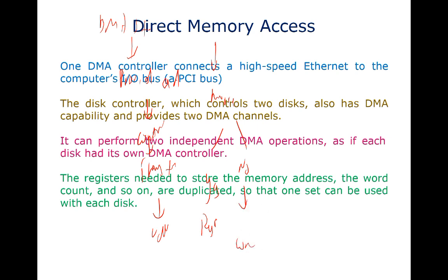Now we also need to know what happens when the DMA transfer completes. The processor is freed from continuous involvement in the actual block transfer, and it is notified after the operation is complete. A simple technical example: in the processing unit, the DMA controller is involved using the address, counts, and directions.